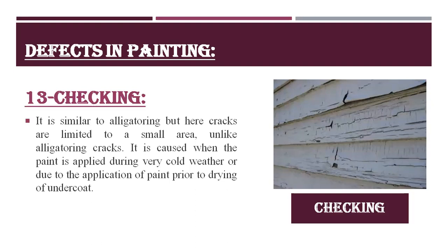13th is checking. It is similar to alligatoring, but here cracks are limited to small area, unlike alligatoring cracks. It is caused when the paint is applied during very cold weather or due to application of paint prior to drying of undercoat.